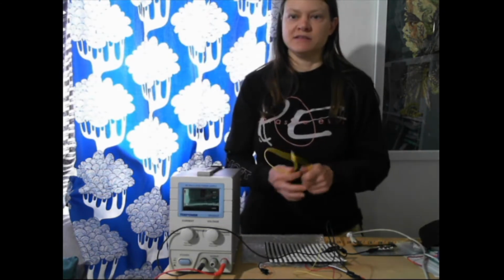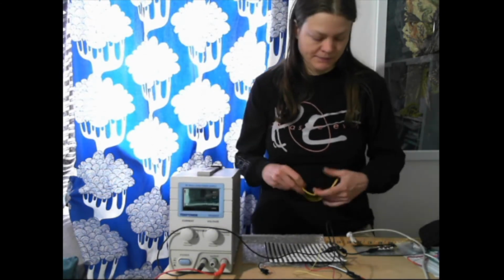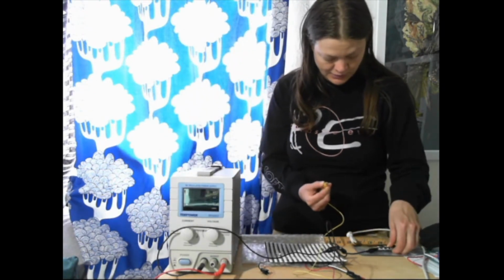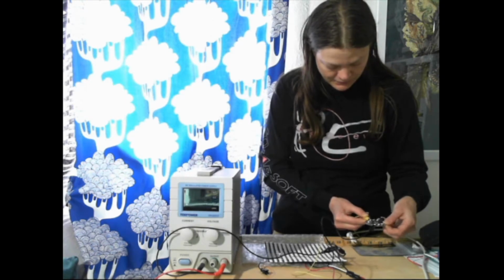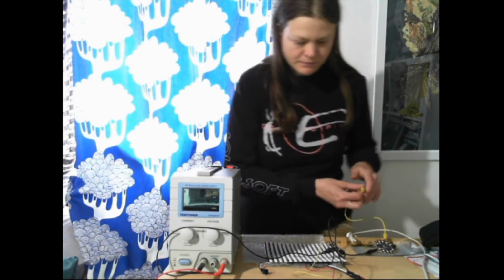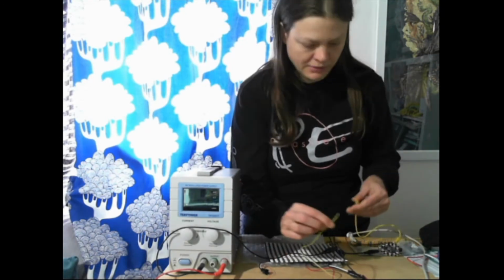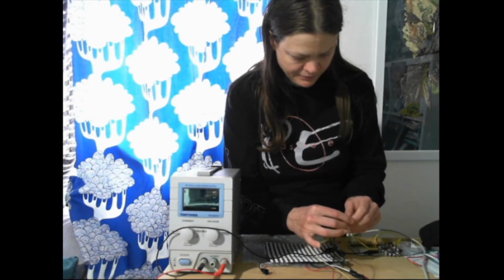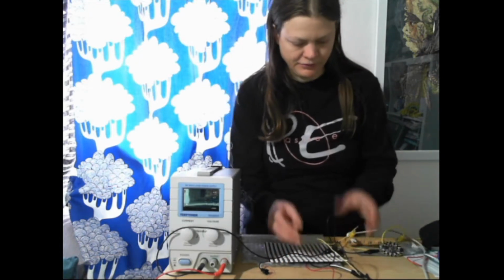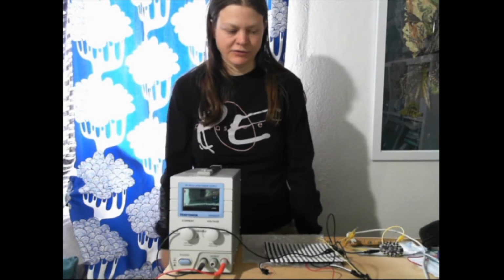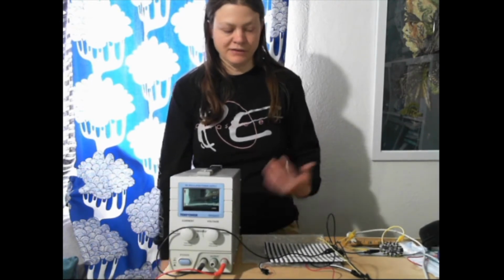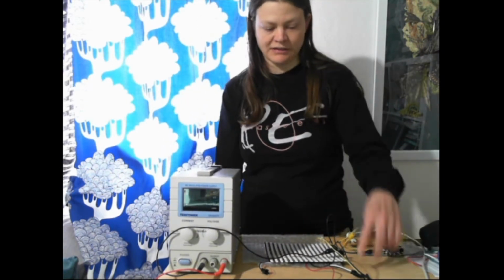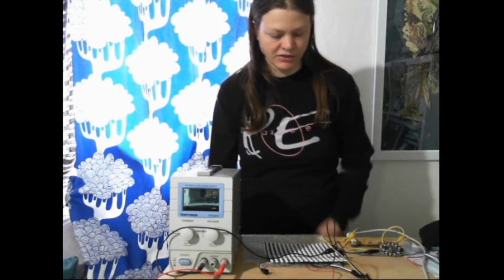And then the next step is get a yellow or blue or green alligator clip. We're going to connect the data line, connect pin A1 on the Circuit Playground, and I've got my little resistor here, so just connect it like so. And if you have trouble with the resistor, it is perfectly fine to skip it. It's best practice, but these will work without it. So you've got that. You're going to connect that to the data in on this left side of the matrix.